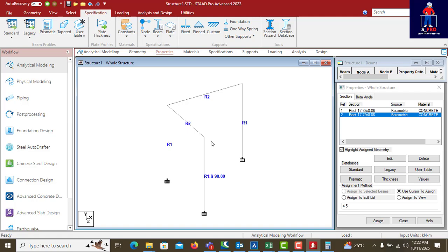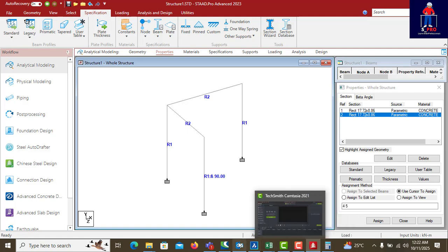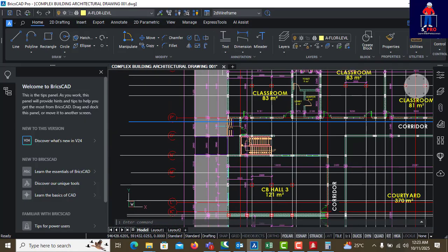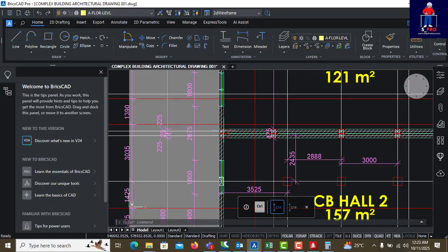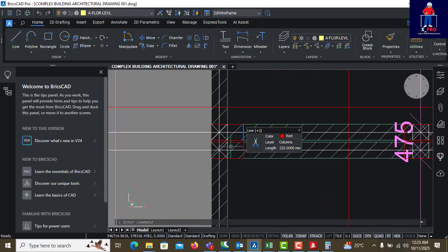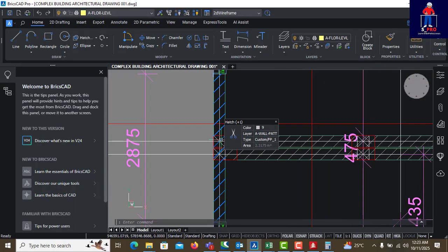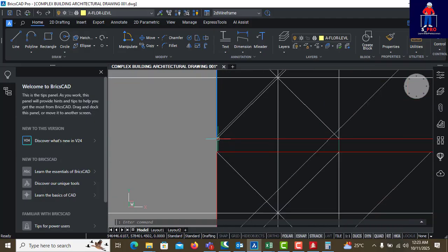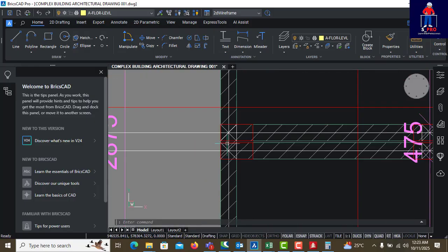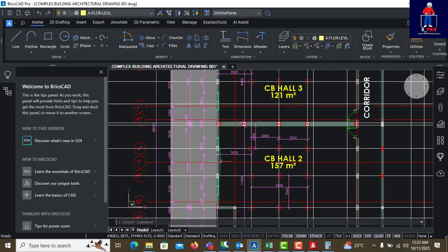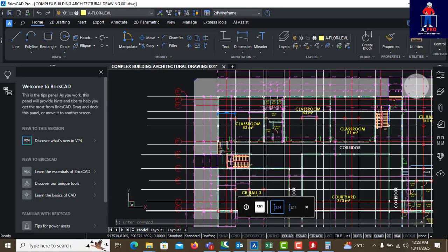So now, where you have expansion joints, like this place, I have expansion joints here. So you see what I did: instead of facing the column in z direction, I now faced it to x, so that this spacing here for the expansion is maintained. You get? So for you to do that, let me assume that this expansion joint is the next in my model. I hope you understand.